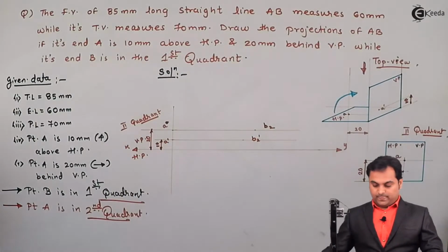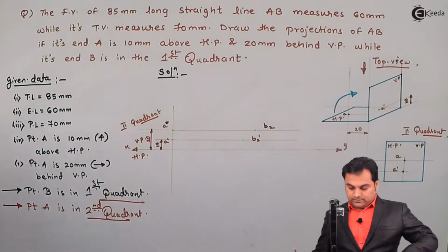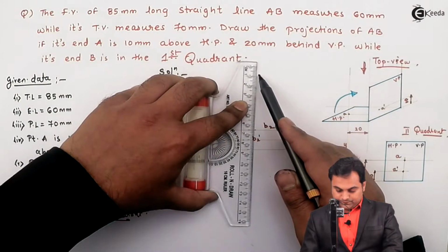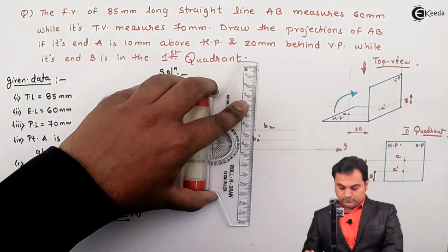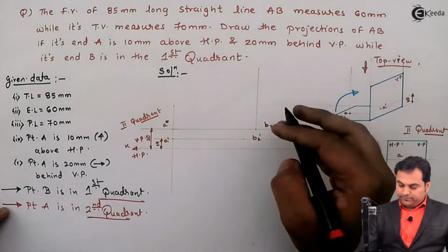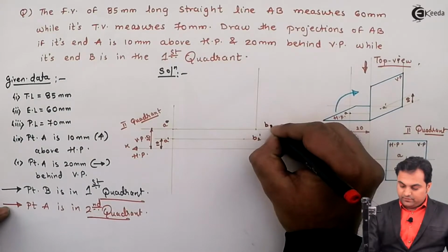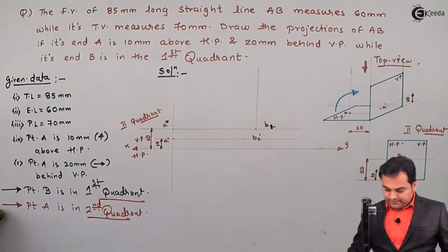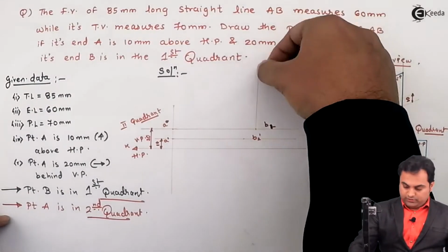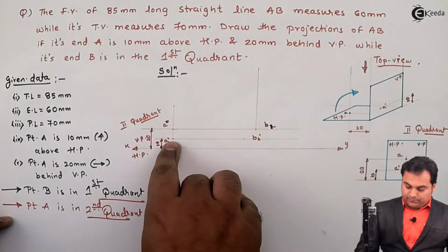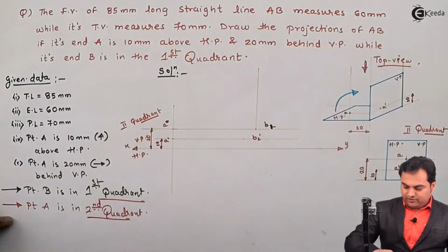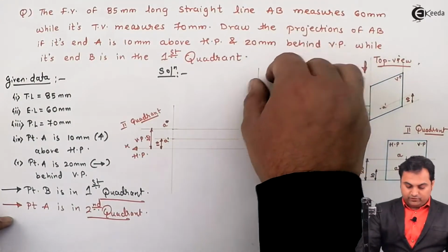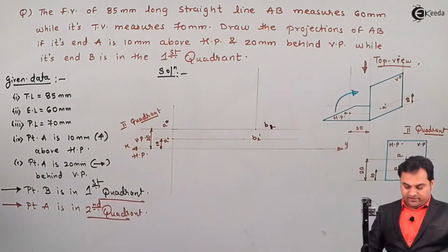Then after this I'll project B2 dash upwards. So here I'll give this point B2, I'll replace it with B1 because that is the standard notation. Next, when I've projected B1 over this from A dash, I will draw a line which will give me the point B dash here, and for that I'll require the true length, which is 85.